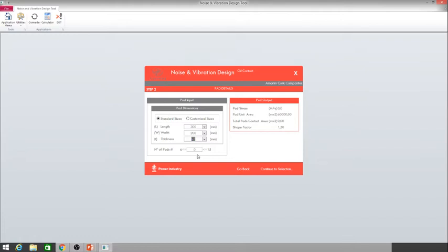Just stepping back, I see that there's no pad stress yet because you have not selected the number of pads. Correct. But you've predefined a thickness, or could I have selected something else? No, the thickness is predefined because you don't have the option, in this case for instance, of the 10 millimeter. Why? Because if you use those dimensions with 10 millimeter thickness, the shape factor will be outside of the limits, so outside of the linear region of the material.